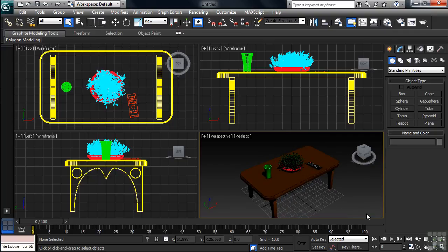Now, the Orbit command also comes with a very special shortcut key. This is one you're going to want to use, so commit to memory the keyboard shortcut Alt middle mouse wheel. You'll be holding both down as you orbit.